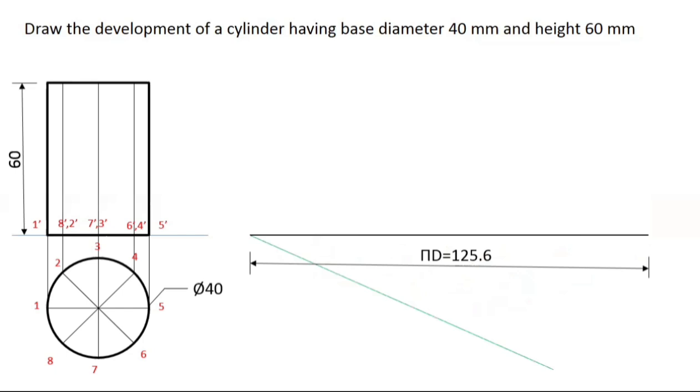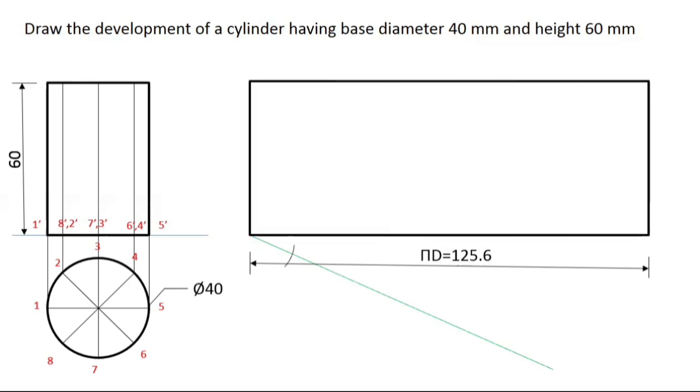Let's see how. Draw a line. Let's take 8 centimeter, that would be very easy for you. 8 centimeter line at any angle, that green line. So open the compass how much? 1 centimeter and put the compass needle over here. By opening the compass 1 centimeter, simply cut right here. First, second, 3, 4, 5, 6, 7 and 8. Just like that. Now join in the same fashion. 1, 2, 3, 4, 5, 6, 7 and 8.